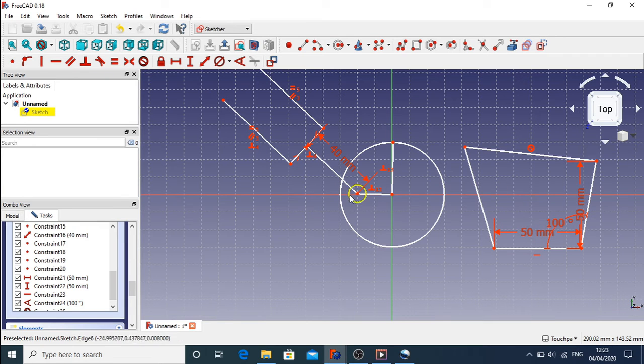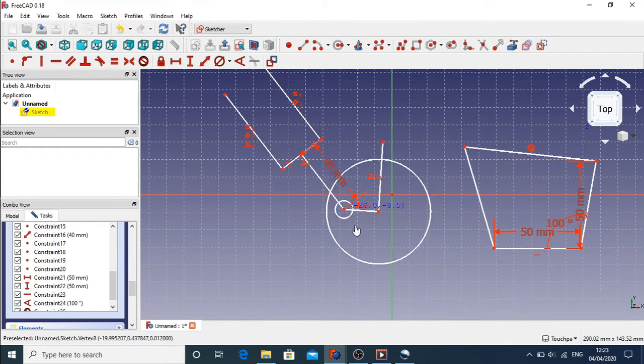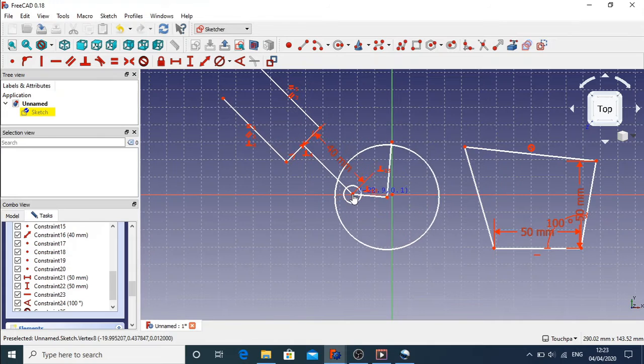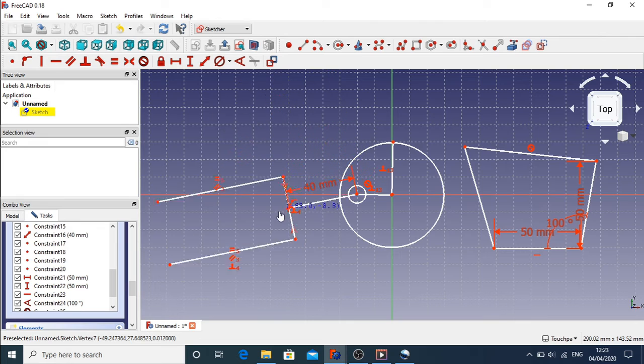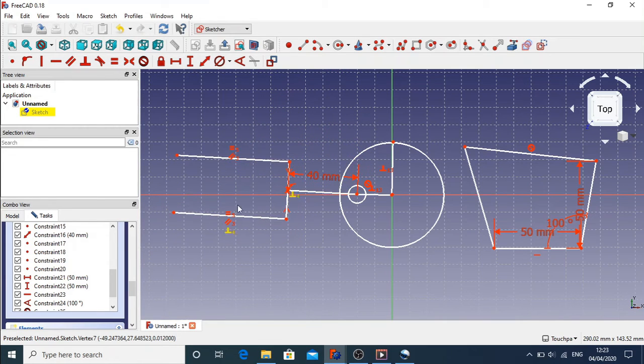And the same for here, we've got quite a lot of mobility in this sketch. So if I create a block constraint on, say, this circle here, I won't be able to move that, but I'll be able to move other parts of the sketch that are connected to it, because the block constraint isn't applied to this geometry, it's only applied to this part of the geometry.